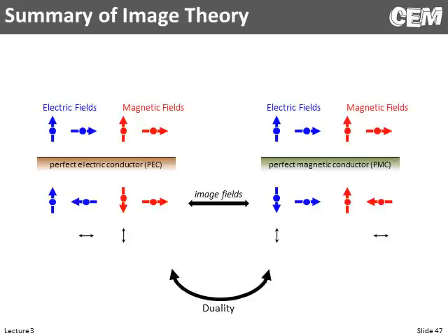Likewise, if the symmetry changes a little bit, you would need to use a perfect magnetic conductor. This is really, really common in modeling where there's this left, right, up, down redundancy. You slice a plane through the middle of it and you choose perfect electric or perfect magnetic, just depending on what kind of fields the device would actually produce.